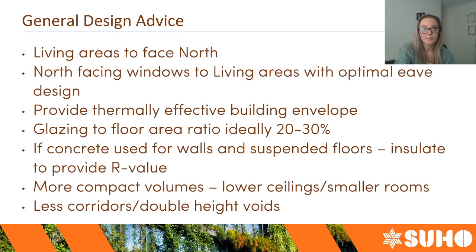So going back over some general design advice, just around what we know works in the software. Living areas should, if possible, face the northern aspect. The windows should have optimal eave design, and we can help you with shadow diagrams and things like that to help you work out what the sun is doing at different times of the day and different times of the year to optimize your eave depths.